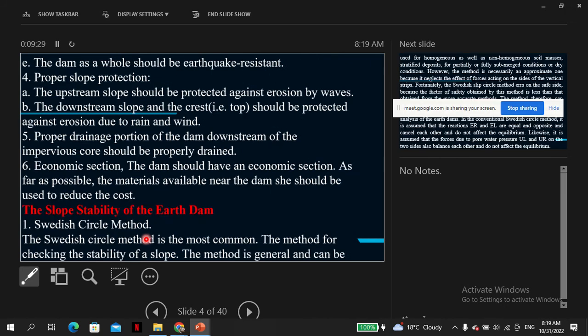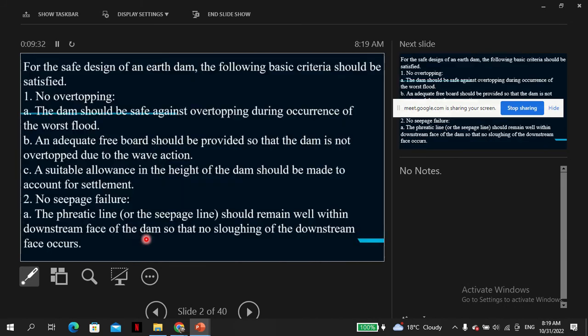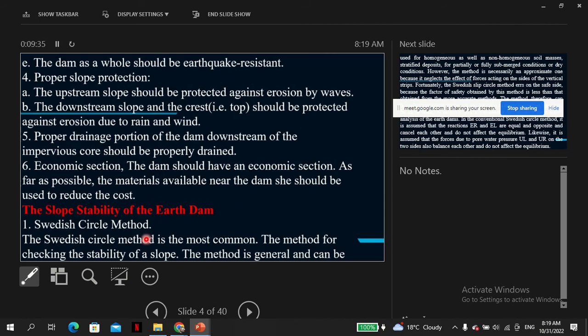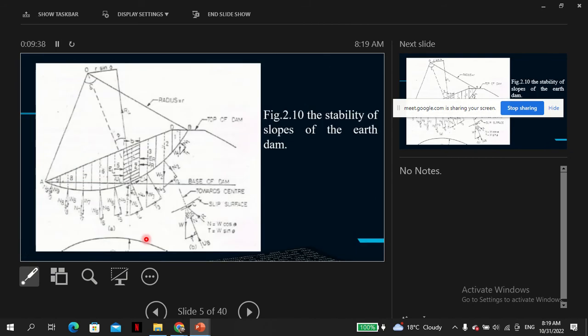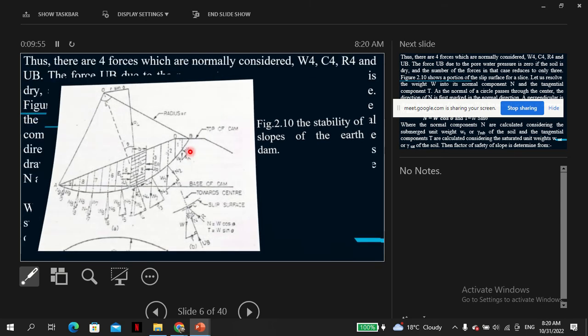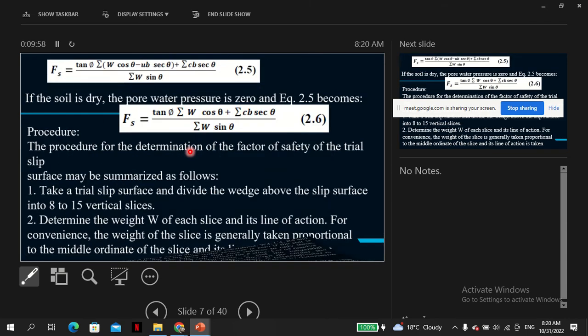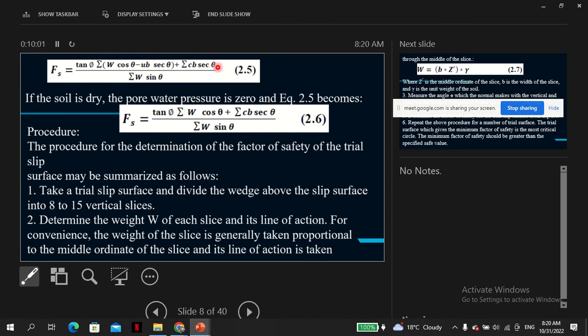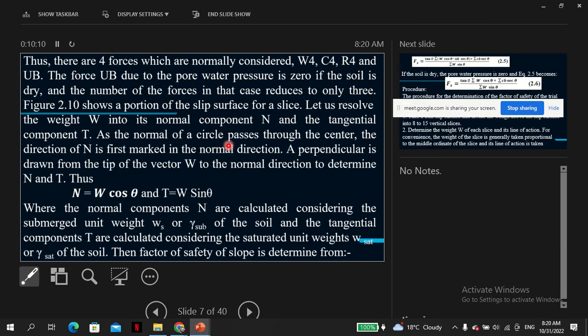So I give you another assignment as well. The factor of safety in that case was determined using forces only. Check also against moment. With the moment, you just multiply these forces by the radius because the center is here. You just know the force times the radius, and then you see what difference you need to make. So here, all this summation has to be multiplied by the radius. The same here by the radius, and see what difference does it make.